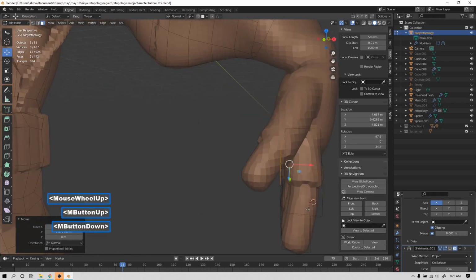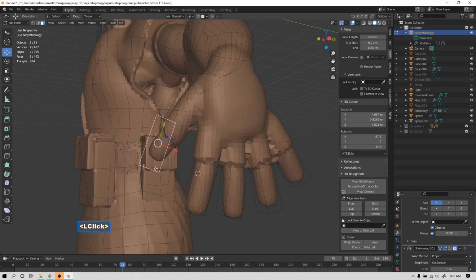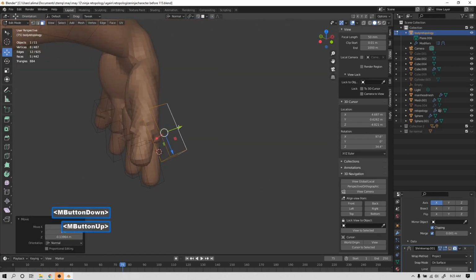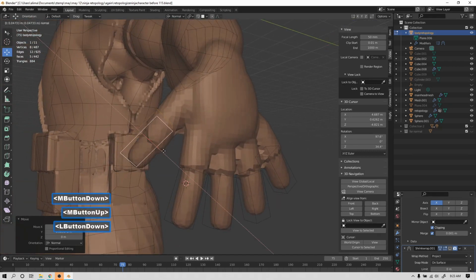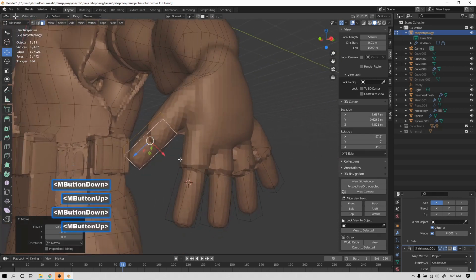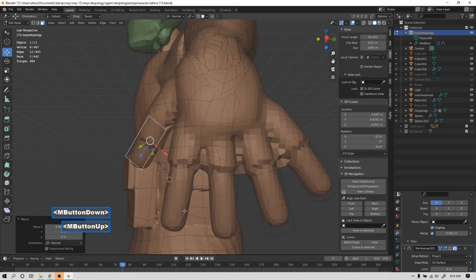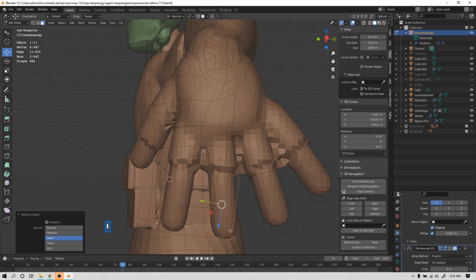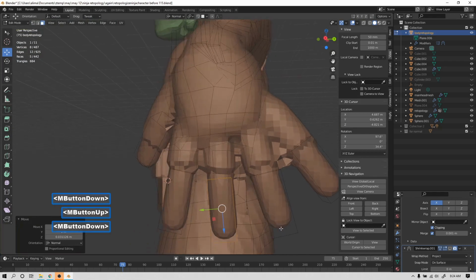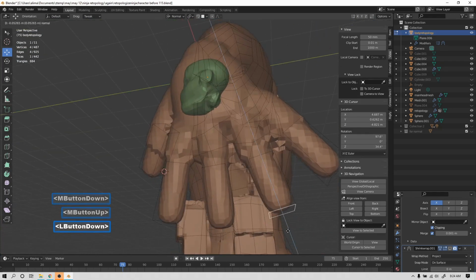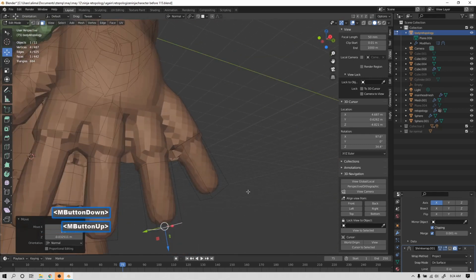You want to rotate in 3D to make sure they're actually where you expect them to be. A lot of times they're not, like you can see this right here. R to rotate on the X-axis. So I'm going to hold Alt, press A, hover here, press L, press R to rotate on the X-axis. Adjust these slightly, press L, R to rotate on the X-axis. Here I'll select this, move that so it's up more. I'm going to hold Alt, press A to deselect.